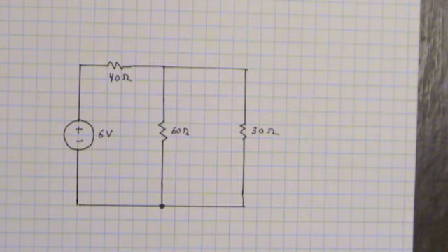Let's consider applying element constraints from our previous lesson and the Kirchhoff current law that we've talked about so far today to solving this circuit, that is to find all the unknown currents and voltages. There are 4 elements, 2 terminal elements, and so there are going to be 4 currents, 4 voltages. That means there's 8 unknowns. Let's identify these on the circuit.